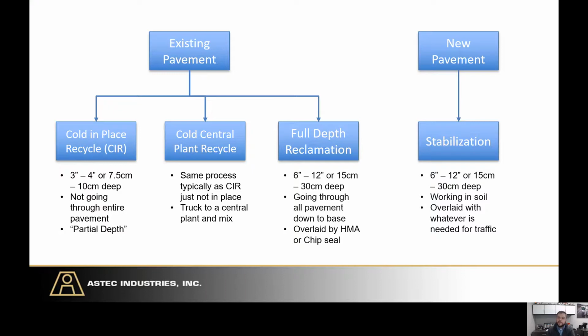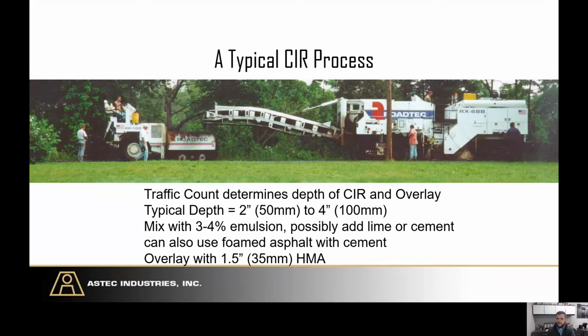What this looks like in application, and this is an old photo, this has been around for a long time in different forms. Obviously, you can see by the age of the equipment and the graininess of it that this isn't a new process. Like any pavement and any process, the traffic count is going to determine depth, structure and mix design. But as rules of thumb, typical depth is somewhere between 2 to 4 inches.